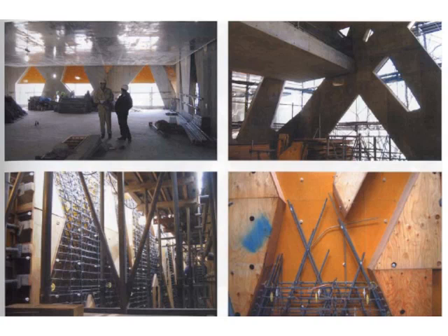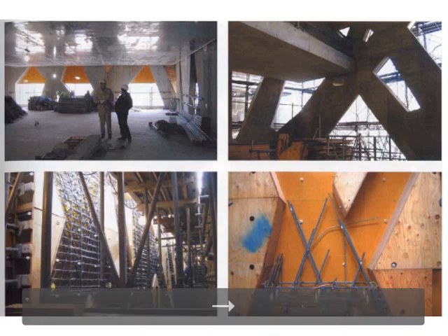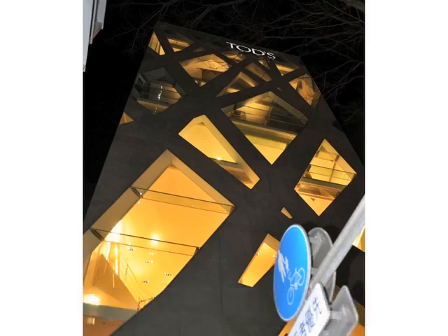You guys remember that from last class. It has very few large aggregate pieces. It's mostly small aggregates. It has superplasticizers in it. It has a bunch of high-tech stuff to get the concrete to actually flow around this material. There's not even enough room in one of these forms to get a vibrator in to help consolidate the concrete. So it took a very special blend of concrete to even be able to build a building like this. But this is the best example of showing how far you can extend this to create a building like this.